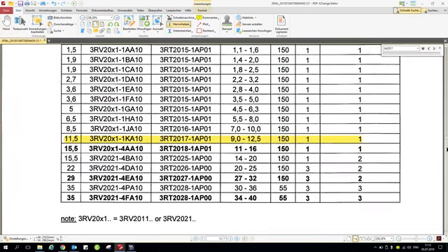And in the section that I have marked, you see that this contactor 3RT2017 has been tested with a 3RV21, which gives us 150 kiloamps, as was shown. Remember that this cannot be changed. This is a type tested combination and no products can be changed.